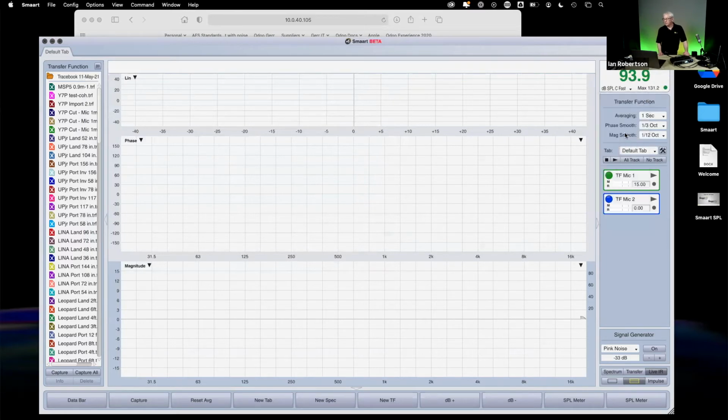And the interesting thing is we use 1K as a calibration tone. And the reason we use 1K is if you go back to the chart in your mind of the different weightings, all the weightings match at 1K. So it doesn't matter what weighting you choose. If you're putting a 1K tone into a microphone, it will always come up at the same level. That's why they all match at that frequency. So I can pick whatever weighting or unweighted that I want.